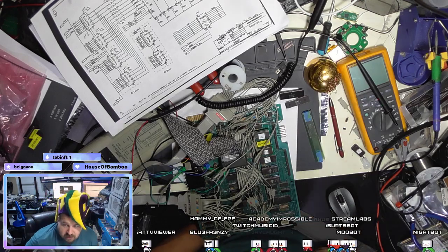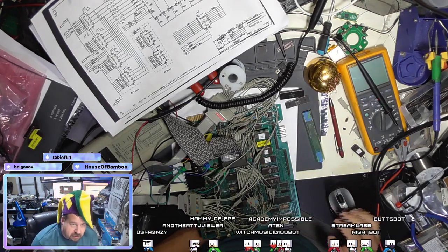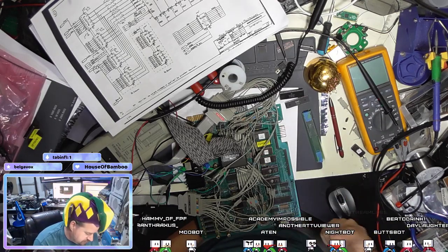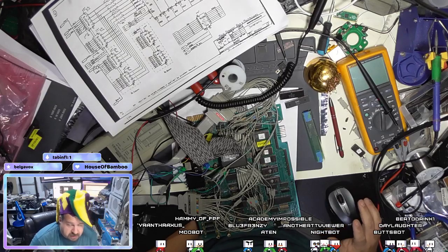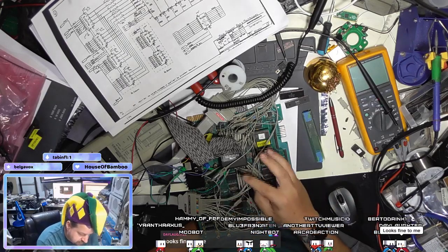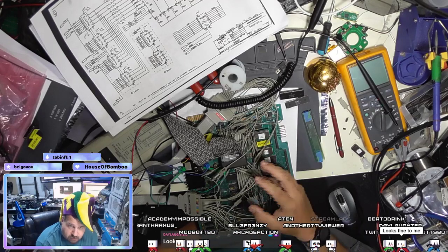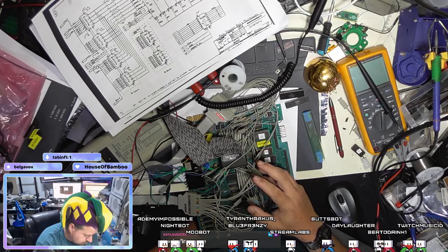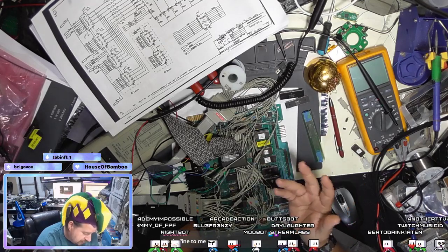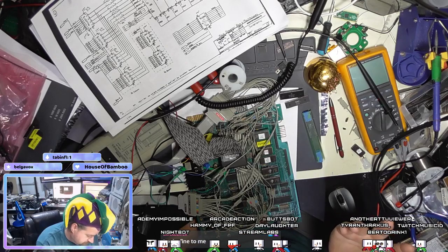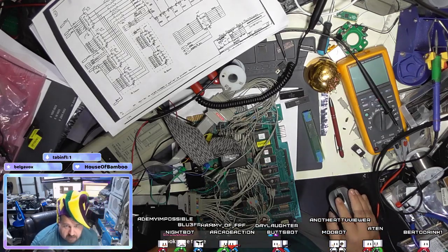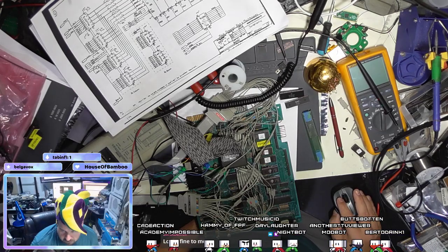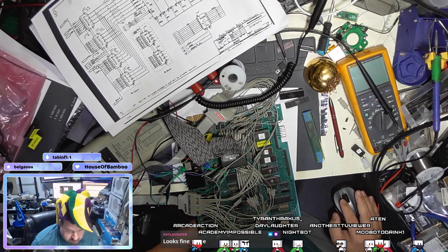So when you're trying to figure out why the IRQ keeps bouncing, or why it keeps resetting, it's not resetting, you're just looking at the IRQ. Which is a good sign. It tells you that the CPU section is definitely working. IRQ is trying to jump to RAM and run from RAM. Not sure why. I didn't write the source code. Maybe if someone wrote a C version of the disassembly, I could figure that out.